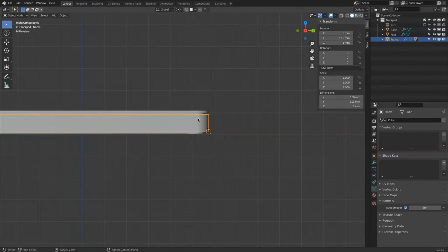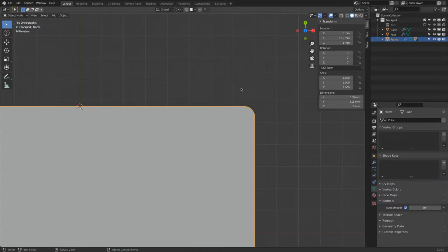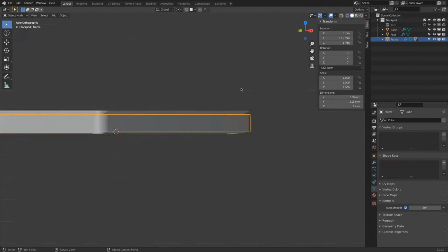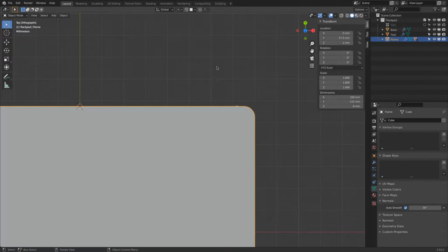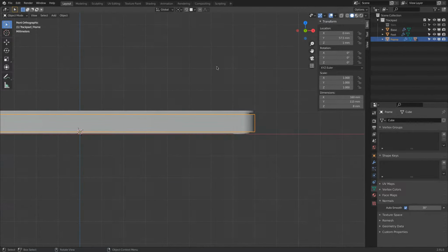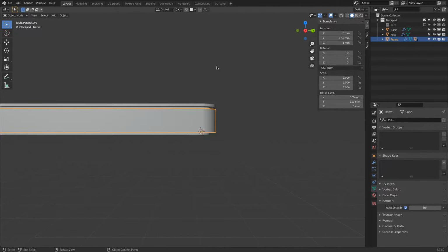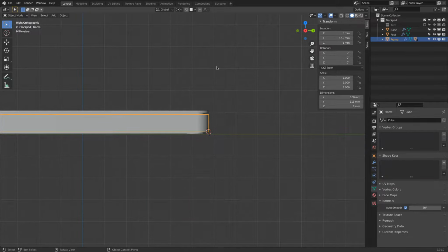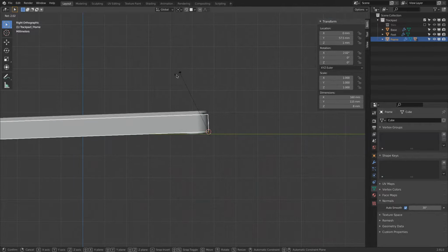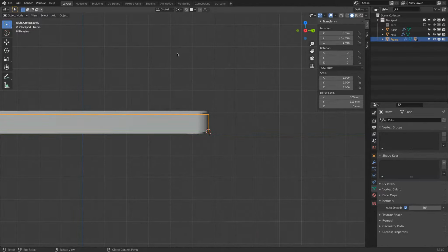So let's go to a side view again. By the way, you saw I started switching my views without clicking on this. I just use 1, 3, and 7 on my numpad, and 5 for perspective or orthographic. Slowly we'll start using the key shortcuts more because they are accelerating, making you work much faster. So R for rotate. In the side view, you see that all follows it.